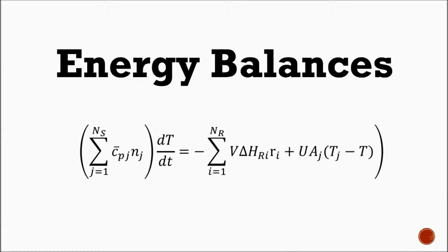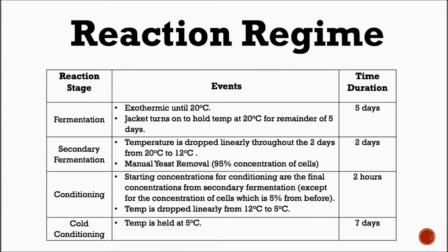Fermentation is an exothermic reaction, so to implement temperature control, the reactor is jacketed. The cooling jacket is also used to implement the temperature drops needed to move through the different fermentation and conditioning steps. All four main stages are completed within a unitank, dropping the temperature to transition through the stages. All stages have been modelled within the MATLAB code.